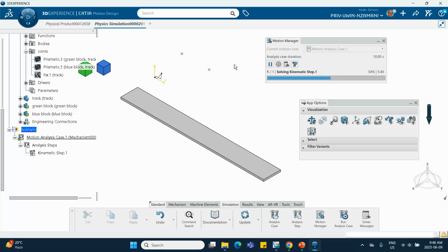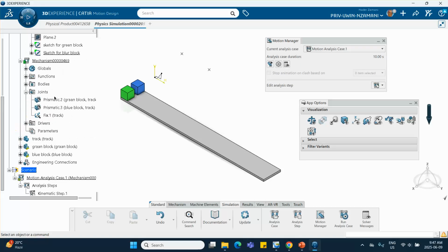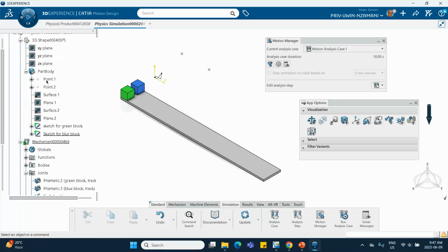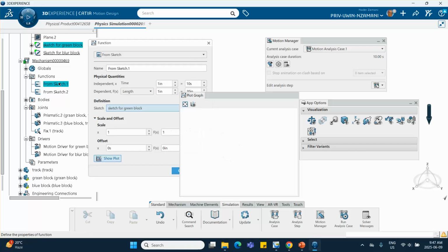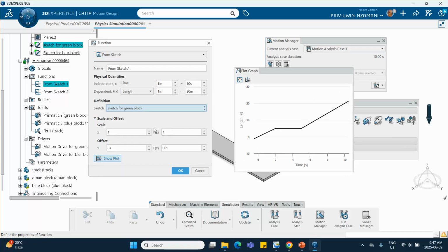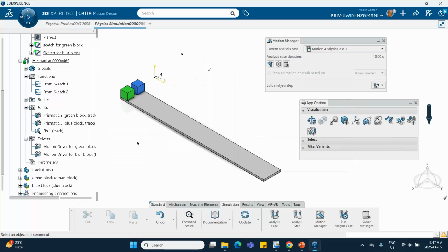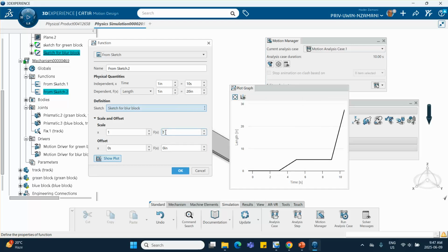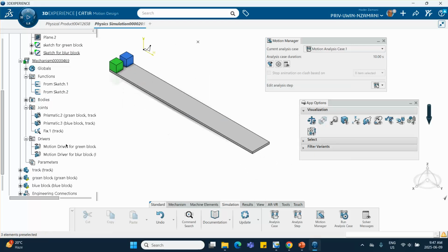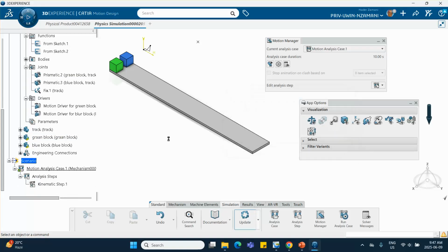So that's where I go back to that function and put a scale as fx scale, I put a -1. So exit, go back to that driver. Either you can go to the driver or you can go to the functions that you have created, either way. Well, I can go to sketch 1. Go to that scale and offset to put a -1 then. Everything is going to get flipped. And the same thing down here. Put a -1. Say okay. Good. And you can update if you want.